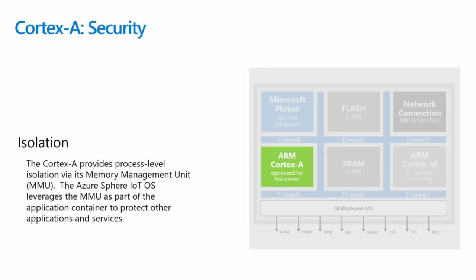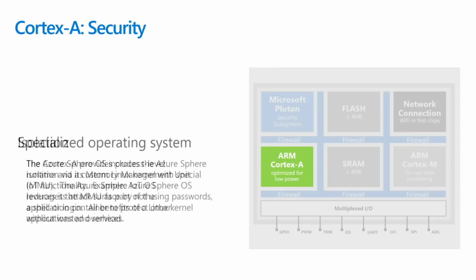So security, basically, because we get isolation. Cortex-M chips don't have MMUs. They don't have address space translation. Having Cortex-A allows you to have process-based isolation, which is what we call meeting the 7 properties for dynamic compartmentalization.